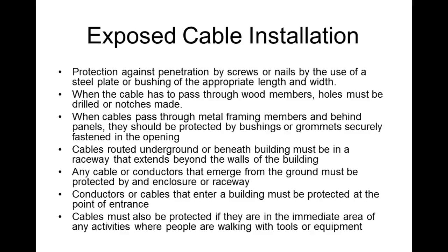Cable troughs, cable routes underground or beneath buildings must be in a raceway that extends beyond the walls of the building. Any cable or conductor that emerges from the ground must be protected by closed raceways. We don't want, especially if you're running conduit, liquids to get down inside the conduit, right?